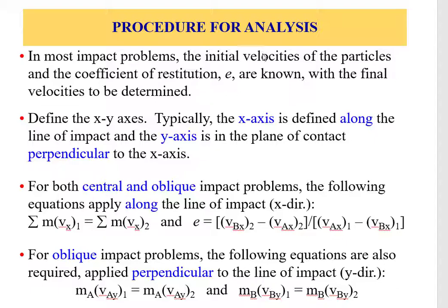So first, gather the information about the problem, determine whether it's oblique or central, and establish the line of impact. Make your line of impact along the x-axis and make your y-axis perpendicular to the line of impact, which will define the impact plane. Apply the conservation of momentum along the line of impact using the vector components, and also apply the coefficient of restitution along the line of impact for both central or oblique.